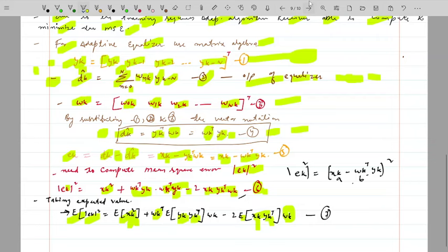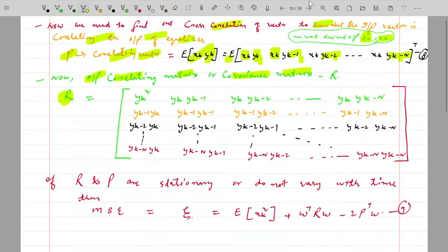So let's move to this, it's taking time. Yes, so here R is the covariance matrix. Firstly, in the first row we have considered simply y of k. Y of k is the first element. This first element is multiplied with all the delays of the same y of k vector, in a matrix form basically. So for y of k, we use an n plus 1 matrix here.